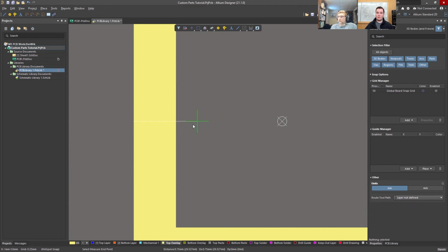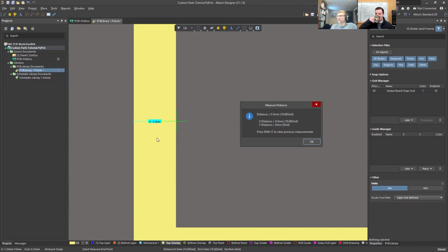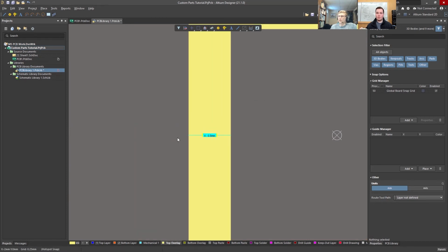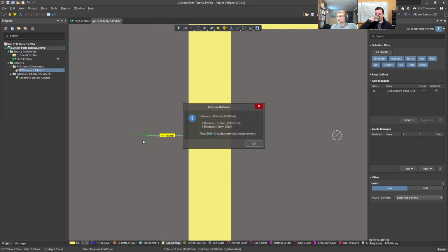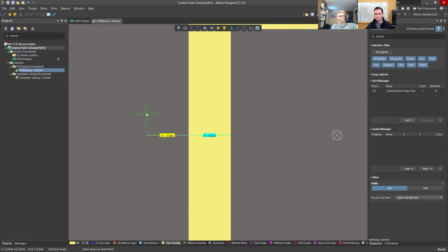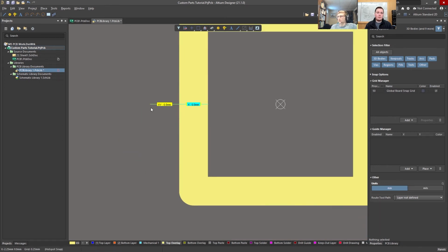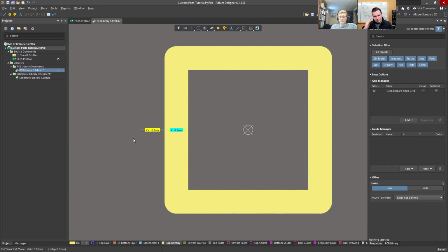I just mean like 0.5. Hold on, you'll see what I mean. Right there. So obviously we made our silk screen 0.5 millimeters thick. So we want our pad to terminate on this back edge. And that should be enough to get a good solder. And then how far out do we want to go? Not too much. Same widths. So we can say, again, 0.5 out. So we need a pad that stretches from this X to this X. And the height, we said 0.875. Cool. We're just adding a little bit on each side. Right. All right, so let's do it.